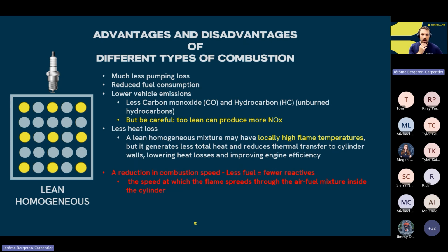The disadvantage now, we have a reduction in combustion speed. Like I said, less fuel equals fewer reactants. And when we say that we have a reduction in combustion speed, basically the speed at which the flame is going to spread through the mixture inside the cylinder is going to be slower. And when we say slower, we mean less powerful. So we do have a loss of power for the engine.